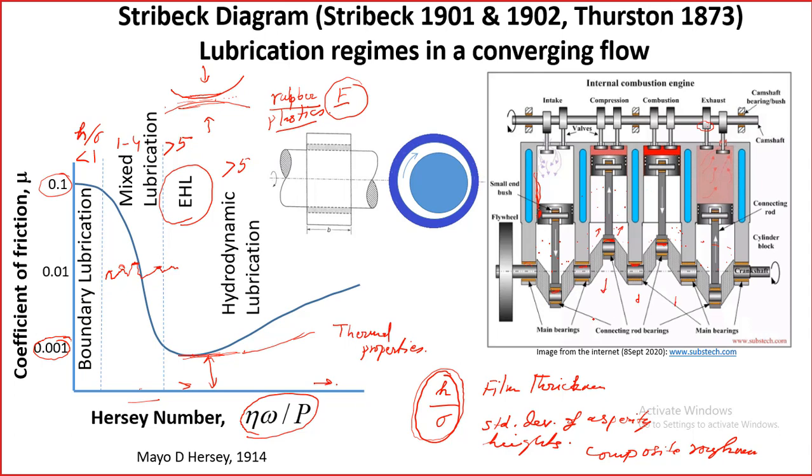drip down, and finally at the bottom you have a sump. The lubricant will get collected into the sump, and from here it will be filtered, and then again it will be supplied back. So this is how the circulation of the lubricant takes place in our IC engines.